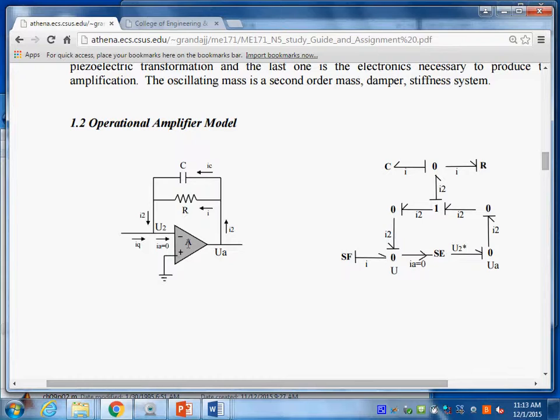That's not the case here. I just want to make sure that everybody understands that the operational amplifier is not a transformer. You may say it is a half transformer, because only one signal is not zero, but really we cannot use the transformer symbol nor the word in that sense, because one of the variables has been suppressed for purposes of what we want to do. So in this case, we could model it as a control source.